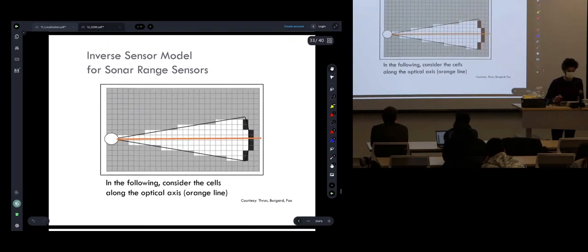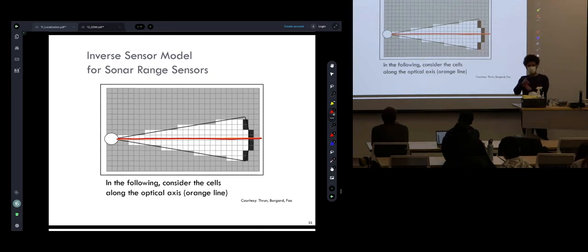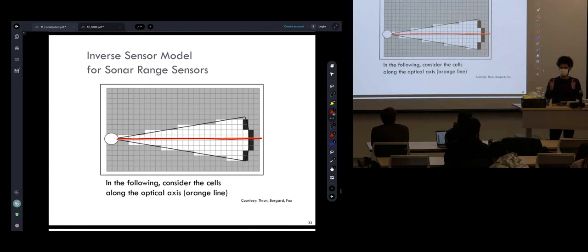So what is the inverse sensor model? If we know that, sounds like we can implement a version of this method. Now, suppose you have a rangefinder that has multiple beams, but for the sake of visualization and conversation, let's take a single beam, this red line. The problem is a single beam is too narrow. If we were only updating cells along the beam, it would take a long time to build a map. So we might assume some thickness for the beam so that when it goes through some cells like this, we end up updating more cells as you see here.